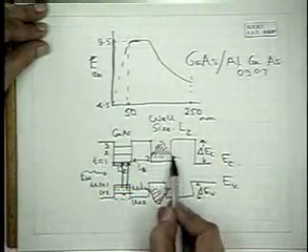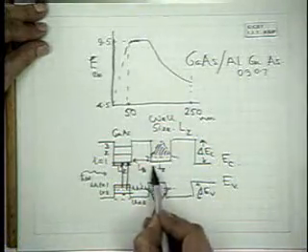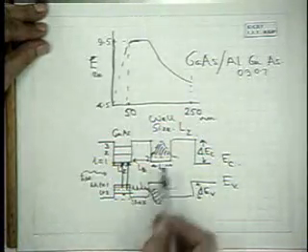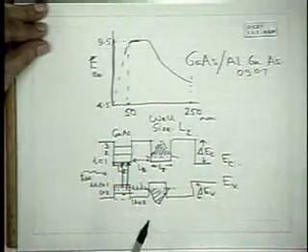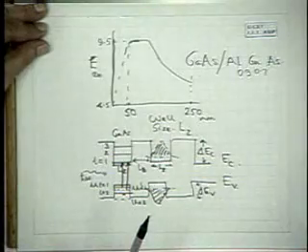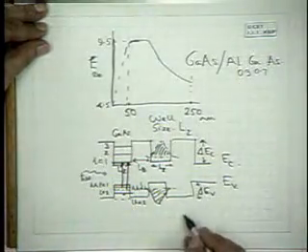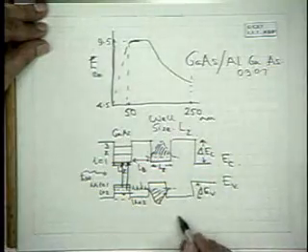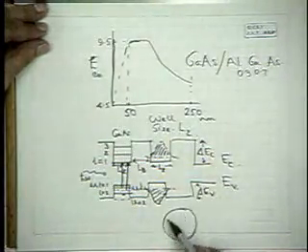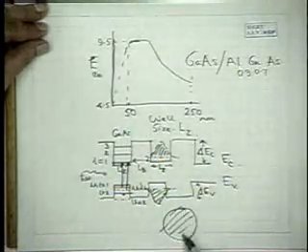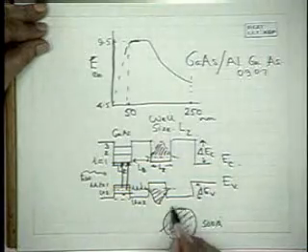So the extent of the well width Lz may in many cases be less than the diameter of the exciton. In the bulk, suppose the exciton diameter could be something like this. Typically in gallium arsenide, the exciton diameter could be something like 300 angstroms.